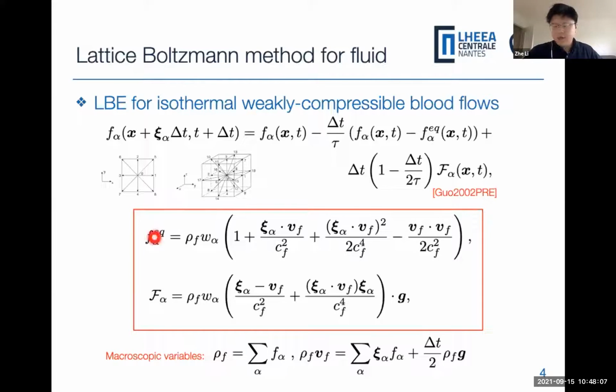Here, this is the equilibrium distribution function, and this is the body force related term. Since we used the force model of Guo, we have to correct the velocity using this body force related term.